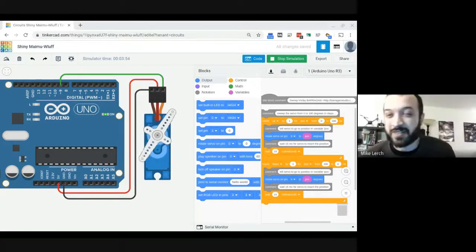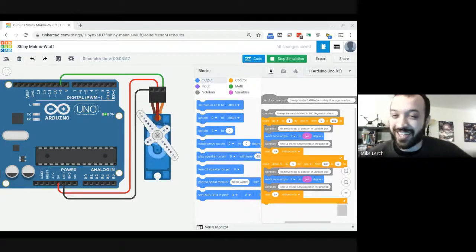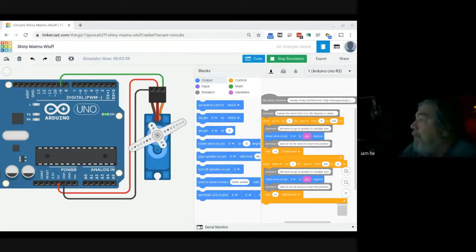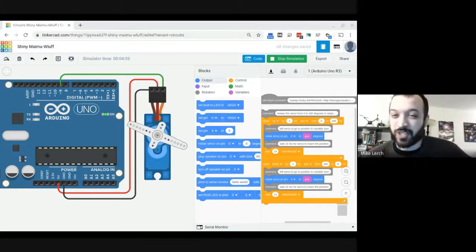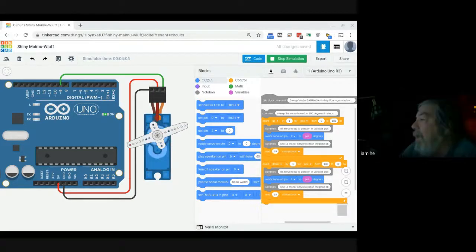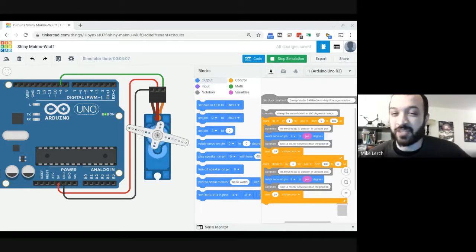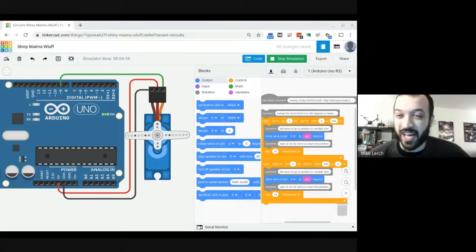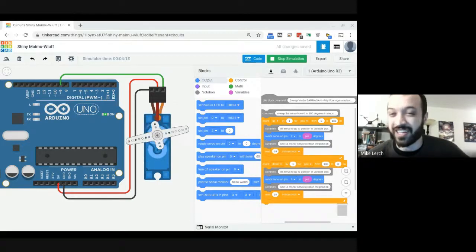And I forget off the top of my head if it's PNP or NPN. I get the 2 confused really easily. I think it was an NPN the last time I looked. Yeah, one draws up and the other draws down. It depends which way you want to pull it. If you want to attach the switch to the ground line and pull, attach ground to the circuit, that means you have power on your circuit searching for ground, and anything that causes that ground will activate your circuit. Or you put it the other way around and attach your switch to the power side. So your circuit's always grounded and it's not applied to power until your switch flips on.